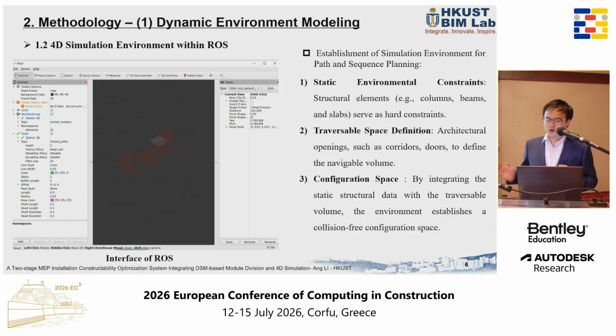With the extracted data, we established a 4D simulation environment within ROS. Here, the structural elements serve as static environmental constraints, and the corridors and doors serve as traversable space. By combining those 2 spaces, we can get a continuous collision-free configuration space. Within this configuration space, we can guarantee our simulation results comply with real-world application.